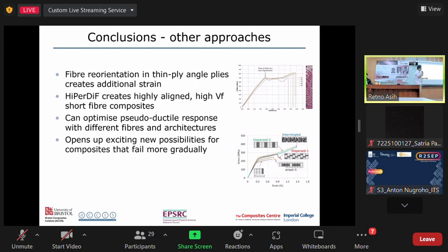and for the discontinuous carbon and glass fiber. The key is that we need to redistribute the load and make the failure propagate slowly. That's the key, and it is dictated by the thickness of the carbon layer, the thickness of the glass layer, and also the stiffness ratio, strain ratio. Yeah, also the fracture toughness.